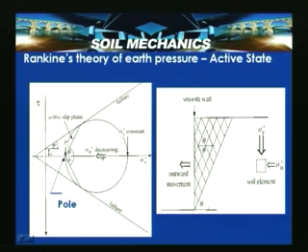So, when sigma h decreases, the initial Mohr circle is somewhere here, and then it decreases up to sigma a and attains the failure plane. So, this Mohr circle is developed, and it is nothing but the failure Mohr circle at the active state. So, Rankine's theory of earth pressure in the active state, when represented in Mohr circles, looks like this. Each and every element here attains failure and plastic equilibrium, reaching the active state of plastic equilibrium. So, this condition is represented here.